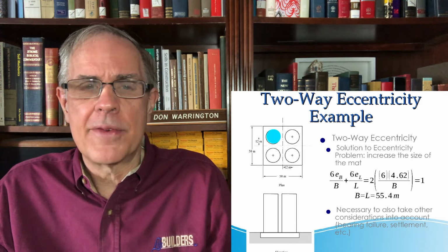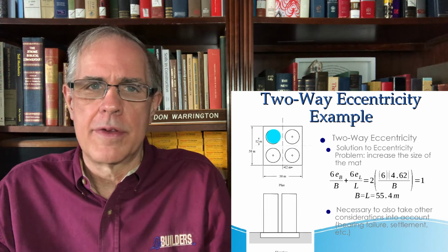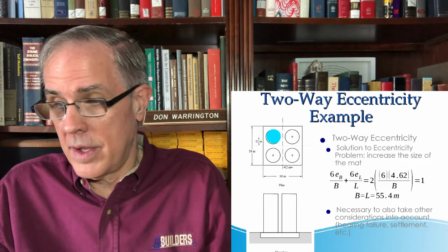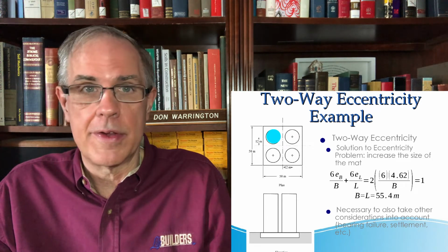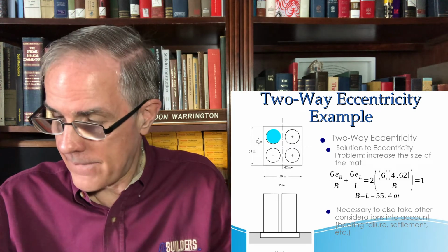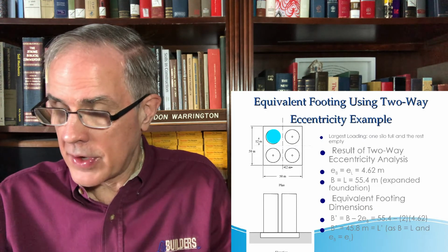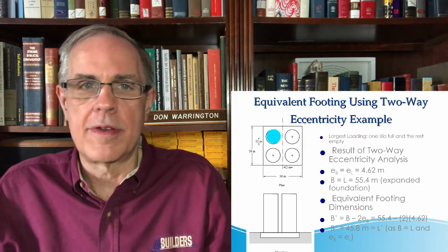That's an amazing result. We've got 2 silos loaded. You think, well, that's going to be the worst case, or at least worse than this. It's not. Actually, the worst case is you only load 1 silo. Okay? Now, there's a couple of ways of dealing with that problem, one of which would be to increase the size of the mat.